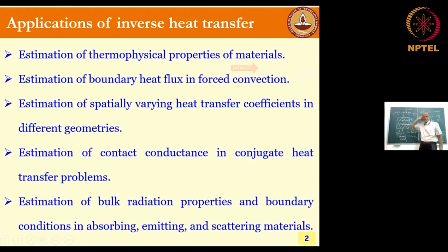We will tell you. And sir, why inverse problem, sir? I'm a super student in heat transfer. I will directly get the contact conductance. Oh, how will you directly get the contact conductance? Please note that the contact conductance will be a function of what these two materials are, the surface roughness, how much pressure you are applying, what is the joining technique. So it is very customized.